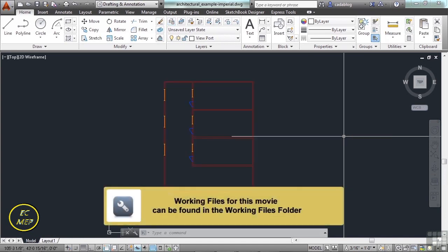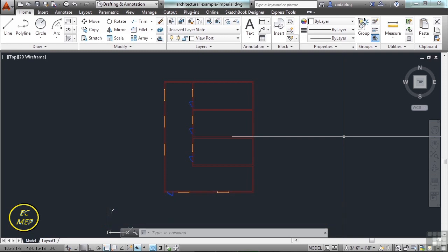You can make drawing layers invisible either by turning them off or by freezing them. We've briefly mentioned them in the last few sections, but I want to take a better look at them so you can better understand when you want to thaw something or when you want to turn it off. Turning off or freezing layers is a very useful thing to do if you need an unobstructed view when working in detail on a particular layer or set of layers, or if you don't want to plot out details such as reference lines or other things like that. And whether you choose to freeze layers or turn them off depends on how you work and on the size of your drawing. Turning layers on and off.